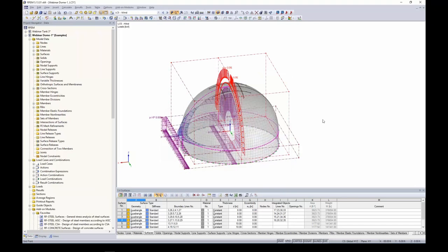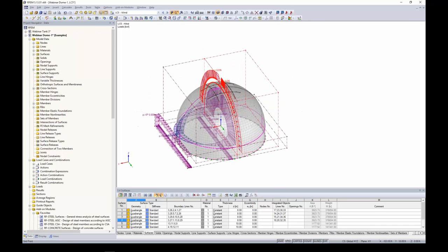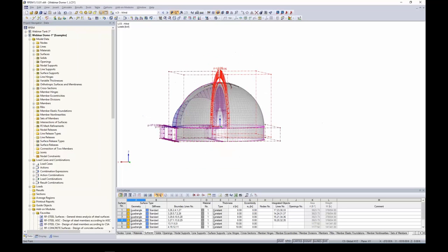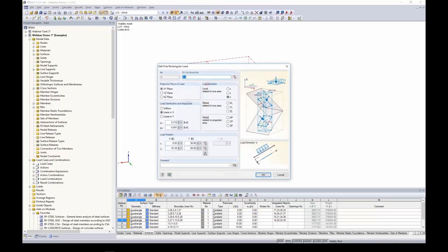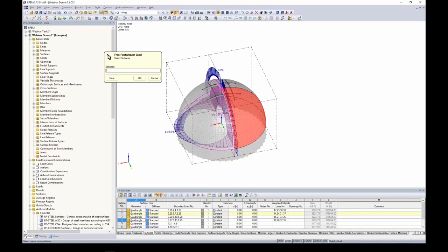So I click OK, and now that free rectangular load was applied to the back of the structure, but we need to make some modifications according to the pressure. So let me go back to creating a visibility by selected objects. I'm going to double click on this free load in the back. Now this is not applying to surfaces in the front, but rather only the 2 surfaces within the back.